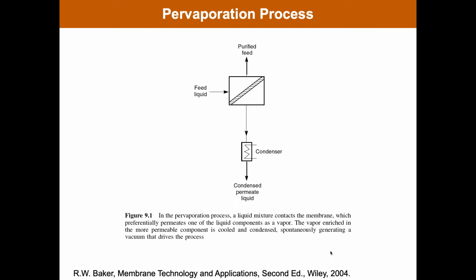Now you've got a gaseous permeate. If you take that to a condenser, what happens? It condenses, and when you condense a vapor, what happens to its volume? Is it reduced a little bit? A lot, right? Maybe 1,000-fold. Factors of hundreds.